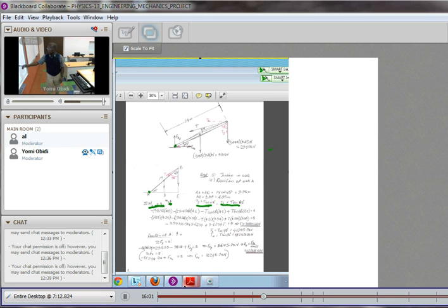We would get this expression, which finally gives us T equals 93,811.48 Newton meters. So that's our T. Now that we have T, we can go on and find the reaction at A. Go back to this expression, and we now have a value for T.